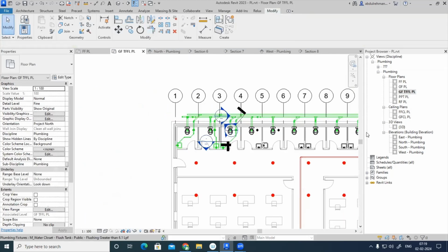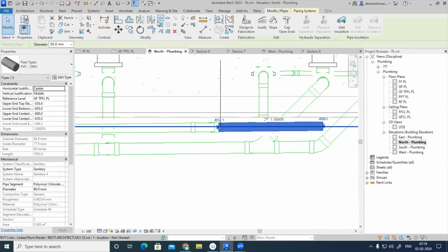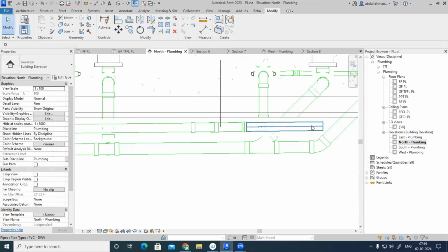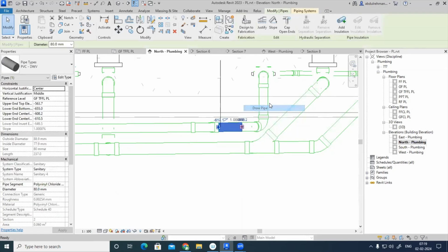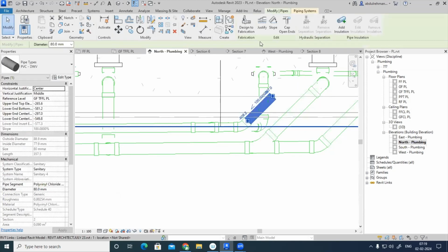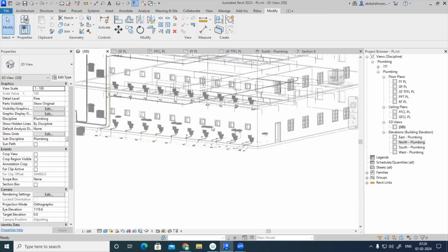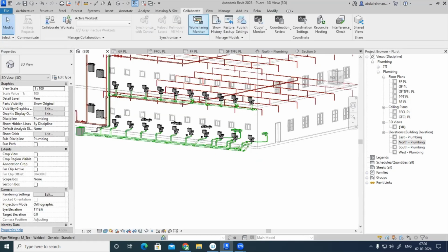Fine. Okay, now I'm just going to the north elevation. Before starting, this is my waist line. Sorry, yeah, waist line. I'll be splitting this pipe. And after that, I'll be selecting here. I'm making a pipe and I'm taking until the floor level. There I'm capping it, because I'll be providing a rodding eye there. Correct, like this. Any clashes is there? Normally clash will not come. If you are having clash, we can slightly check it, because I have offset accordingly I'm arranging.